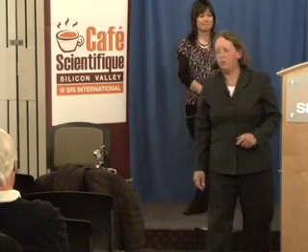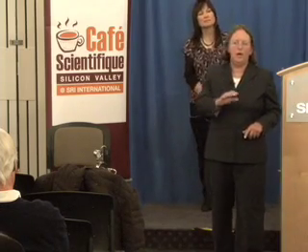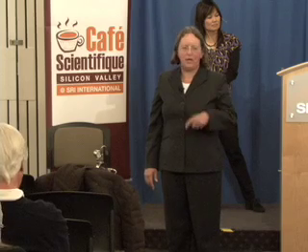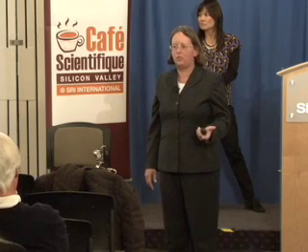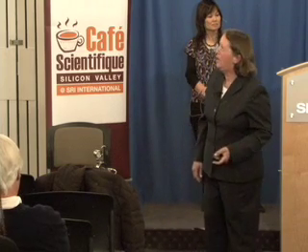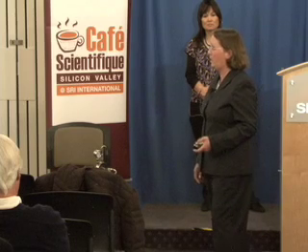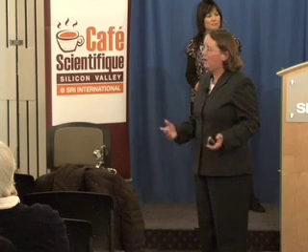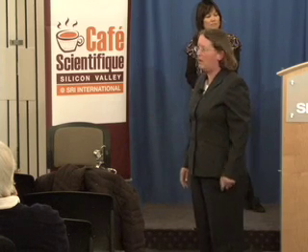EPA always recommends that everybody should have their house analyzed for radon because you really don't know. California is what we call a zone 2. Nationwide, the nation is split up into 3 different zones for radon, and California mostly is considered sort of mid-risk. But if you haven't tested your house for radon, you should do it. It's a pretty cheap test, $10 or so. It's probably a little bit more than that now, but it's actually a very inexpensive test. And it's good to know because if you do have a radon problem, it's really pretty inexpensive to remediate it. These subslab depressurization systems run around $1,500, $2,000. They're not horrifically expensive.